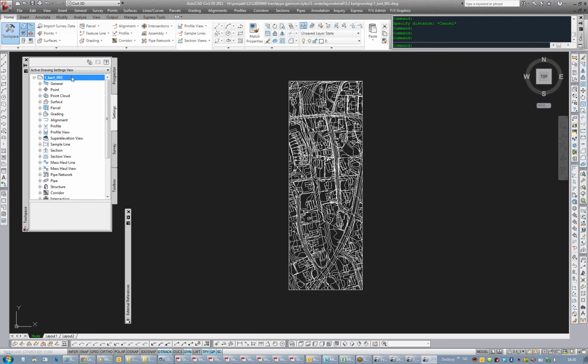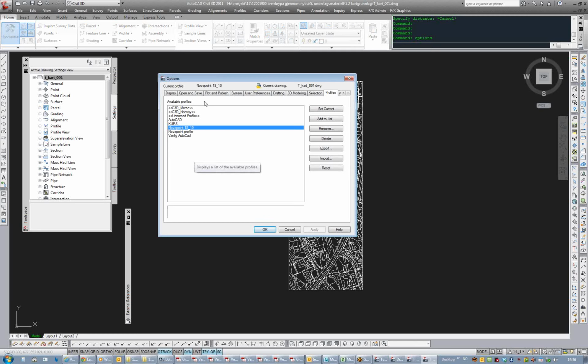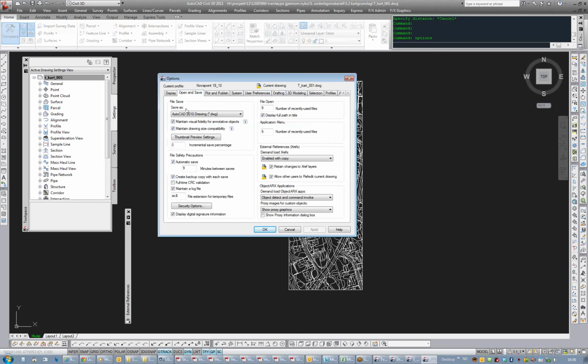And now your coordinates. And that's me every time about this drawing, right? But as far as Civil 3D is concerned, is it going to have to do it every time, or can I set it? If you go into open and save, and find the template file.